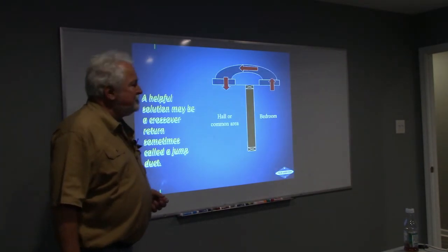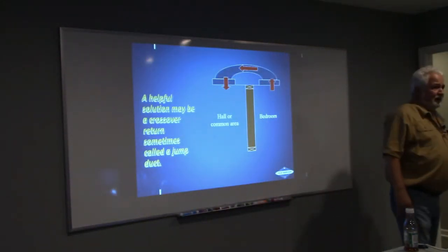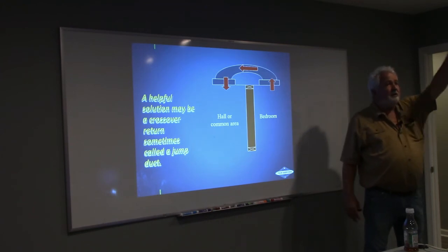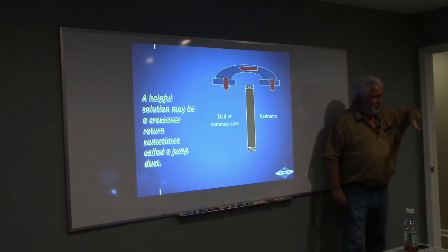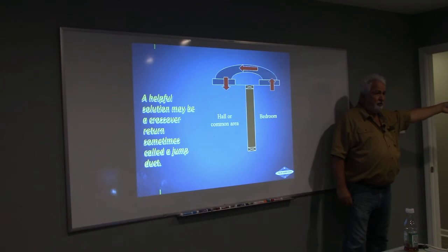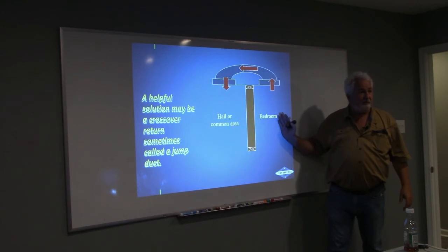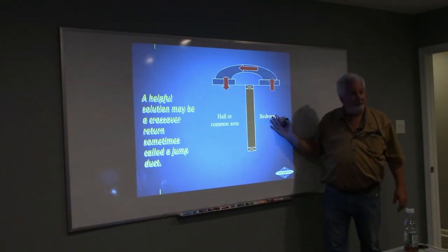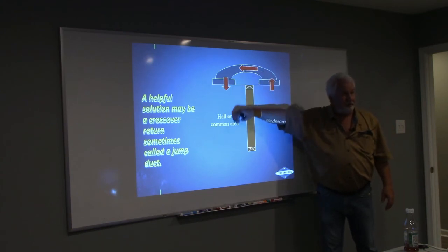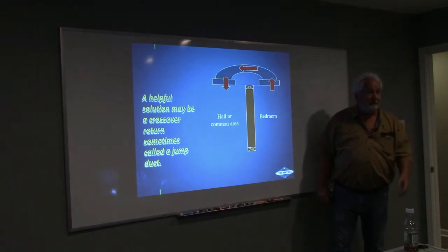All right. So what can I do if the unit's way on that side of the house, and I don't want to run a duct from here all the way back there? Could I just put a jump duct from the bedroom over the door into the hallway? Good, because then when they close that door and this room goes positive, where is all that air going to go? Right back over. Because the return is pulling this negative and the supply is pushing this positive. It's called a jump duct. It runs right back over to that side. Does that make sense? Easy, quick fix, does really, really well.